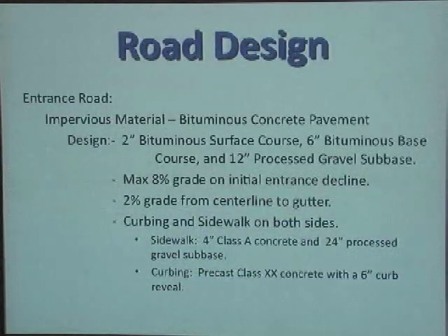As far as the entrance road, we designed it for a 2-inch bituminous surface course, a 6-inch bituminous base course, and 12 inches of a processed gravel subbase. The entrance road had a max 8% grade with a 2% grade from the center line to the gutters to relocate the water to the proper drainage structures.